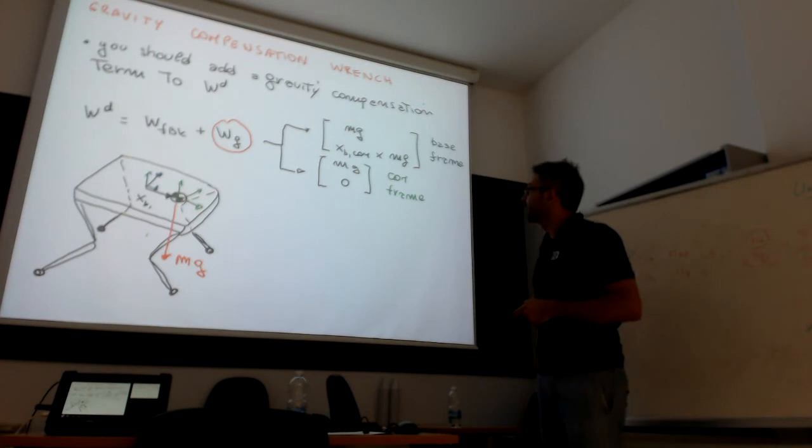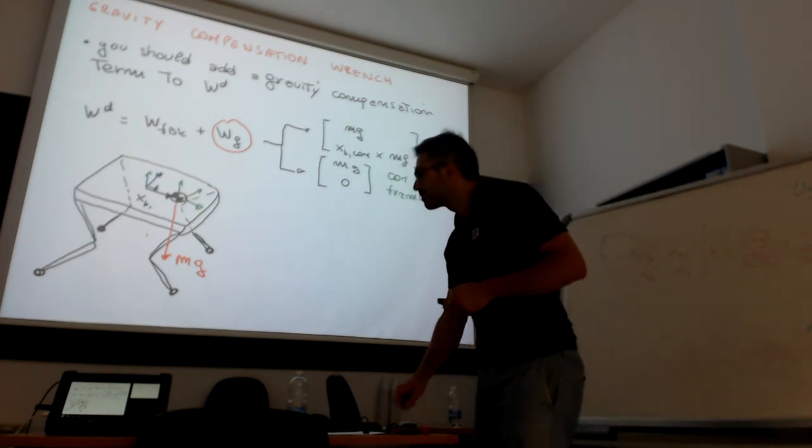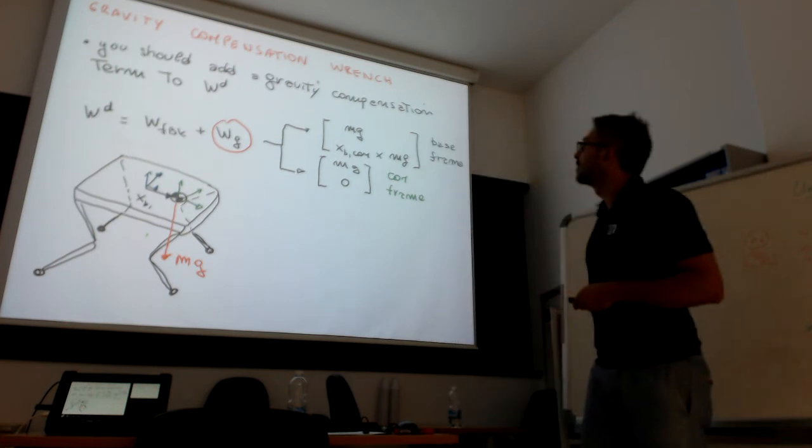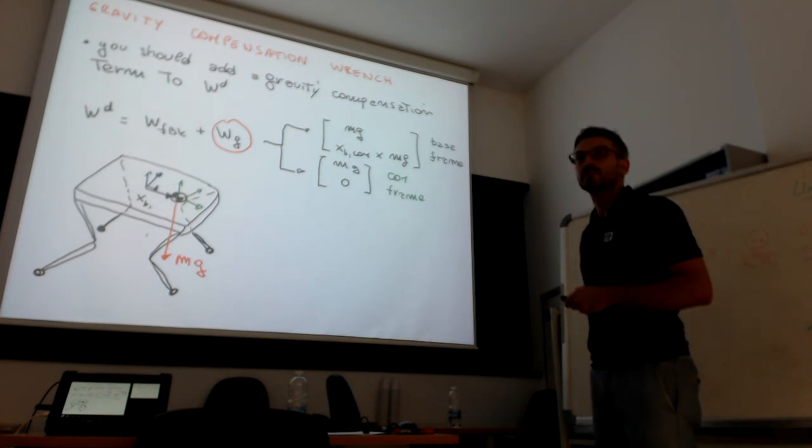So the approach that works is putting here the total gravity. I mean, m is the total mass of the robot. Yeah. Okay, so everything, and then once we've computed F, adding again a sort of gravity compensation at joint level. Yeah.